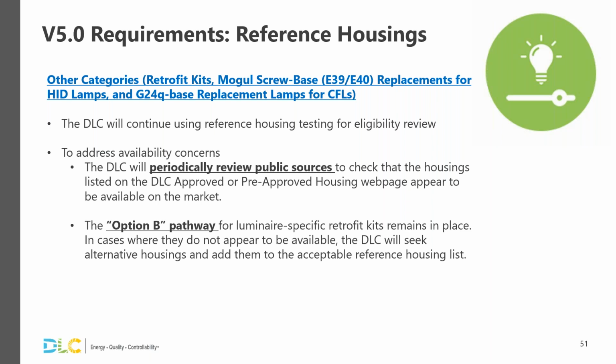So moving on to our reference housing topics. When it comes to retrofit kits, mogul screw-based replacements for HIDs, and G24Q-based replacement lamps for CFLs, DLC will continue to use the current 4.4 reference housing testing policy, where you are required to test in an approved, DLC-approved housing.